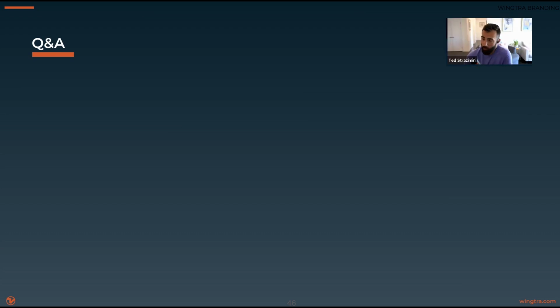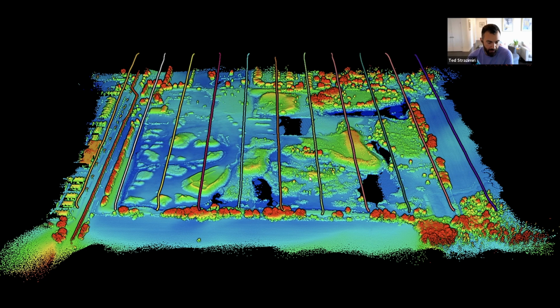So I found the sweet spot to be around 80 meters, 80 to 90 meters. If I switch back here, this is typically what I flew these at. There's a few things to keep in mind. First of all, obstacles, right? You don't really gain anything by flying lower, and there may be obstacles, so why even bother? But you also start to lose returns as you fly higher, right? There's this thing called the probability of detection.